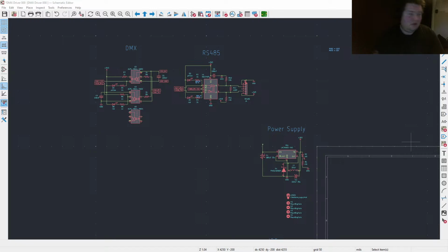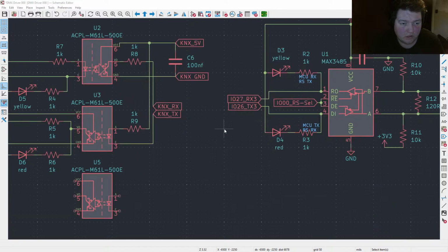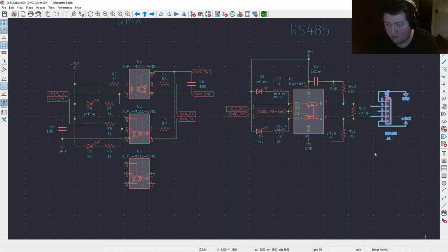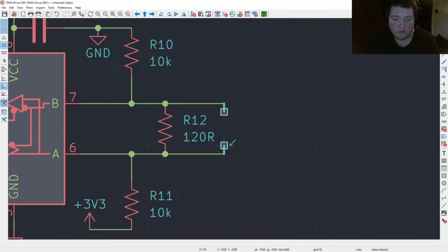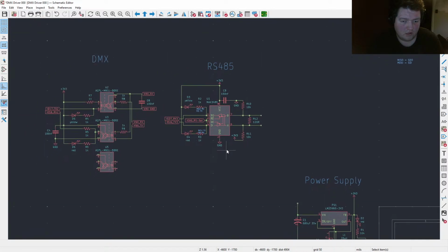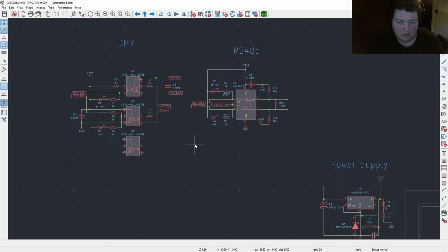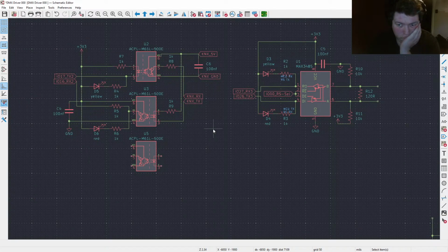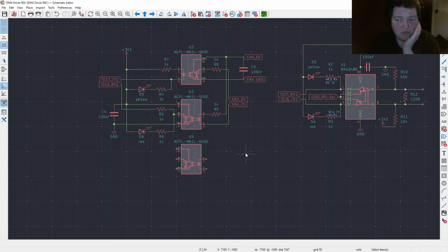Well, if the example schematic I have is correct, then I should be capable of using this one-to-one, which is good. Won't need that connector. And I'll have to put jumpers on this, as you likely won't actually need that. The LEDs are good for debugging, so we'll leave those in place.